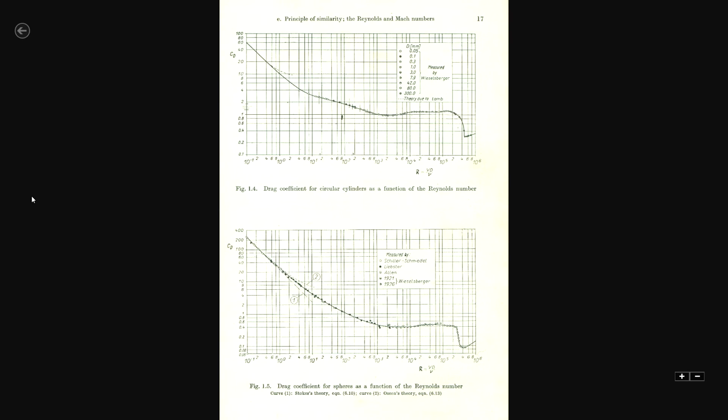Those circles are all experimental values. So, you can see there is an initial part, there is an initial reduction, then near constancy, and then there is a big jump from about 1 to about 0.4. Okay. And then again slowly it increases, and this Reynolds number range here is from 0.1 to 10 raised to 6. So, very wide range.